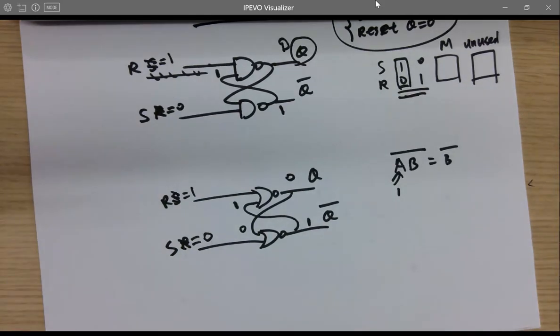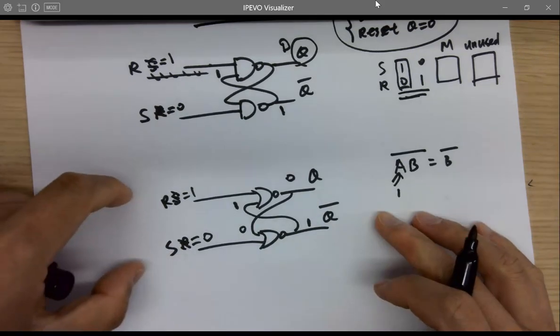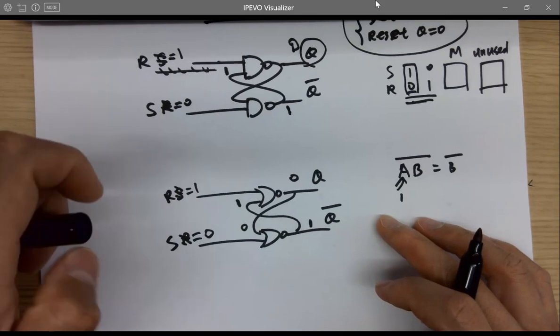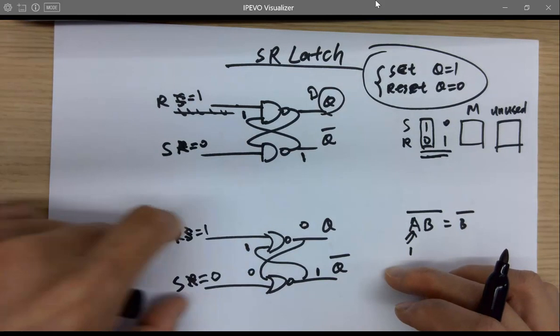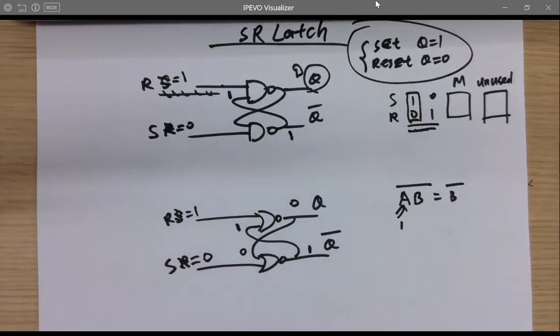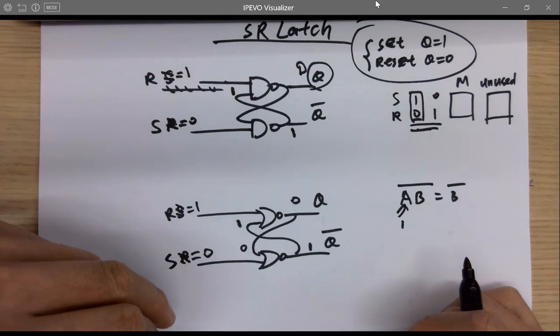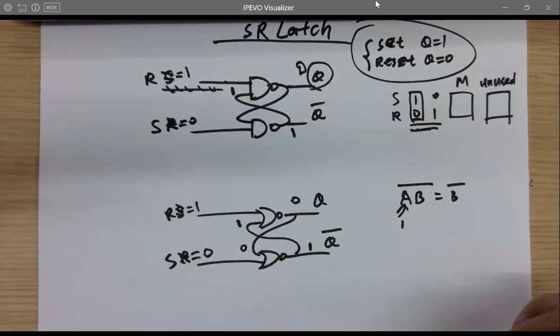Is there a way to swap it? If you use just a regular, I don't know if you should use an AND gate. Oh, if you add another stage, you have to swap it later. It's called a flip-flop. So adding another stage to the latch makes it into a flip-flop. We're going to cover that in a bit. But if you use just NAND gates or NOR gates, they are not being swapped. It's always RS. Easier to remember actually, which is good.